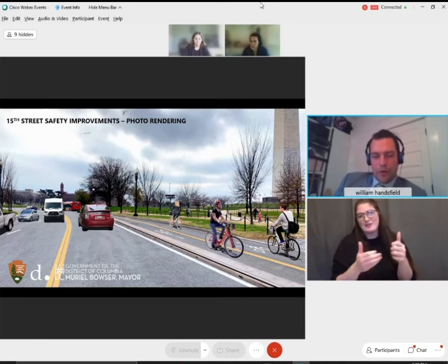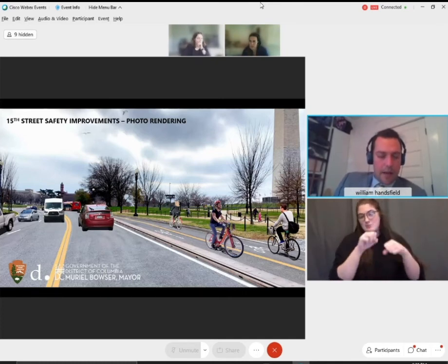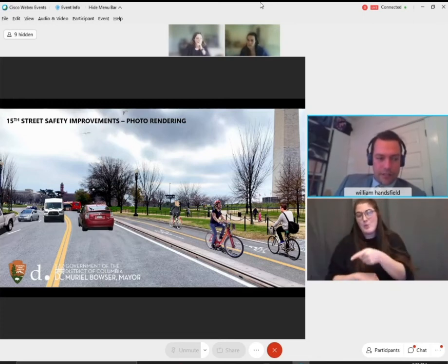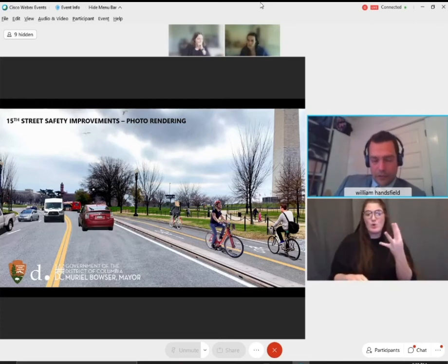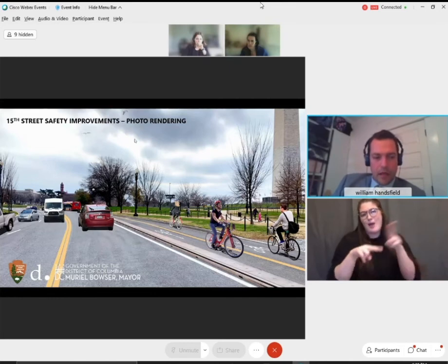We're in this place where we're both trying to really expand our network of bike facilities, protected bike facilities in particular, and upgrade the existing ones. So last year we did the upgrade of 4th Street Southwest and a portion of Northwest, where it was regular bike lanes, and now they're protected bike lanes. So that's a case of upgrading to a much more protected standard.